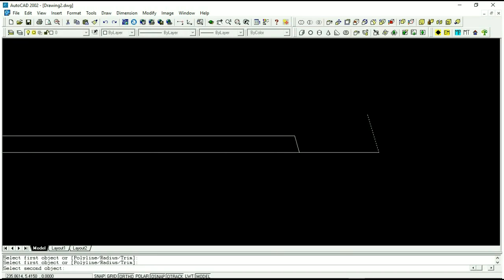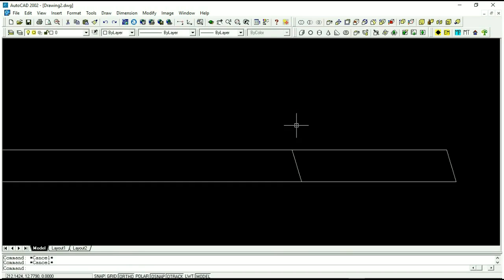So that's the tail. And now I want to make the seat cut. And the seat cut's going to be 4.5 minus that 0.221, which is the hip drop. The reason we need to drop the hip is so that the shoulders of the hip, because of its width, line up at the rafters. Otherwise, the hip would sit up about a 1/4 inch higher. And so when you brought your sheathing across, it would actually have an upward bump on it. It wouldn't be in plane with the rafters. So you have to drop it a little bit because of the width of the dimensions of the lumber.